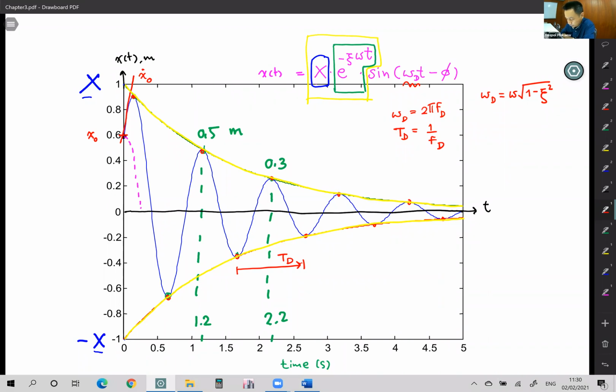Sometimes we use this phenomenon, this equation, to explain how engineers can determine the stiffness of the building if they know how it moves, or how it vibrates. They know the frequency of the vibration. They know the period of vibration. If we can measure the real building movement, we can estimate the stiffness of the building very, very accurately. Okay?